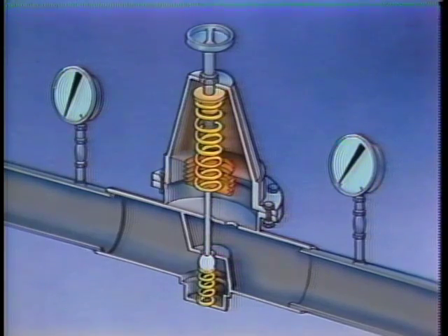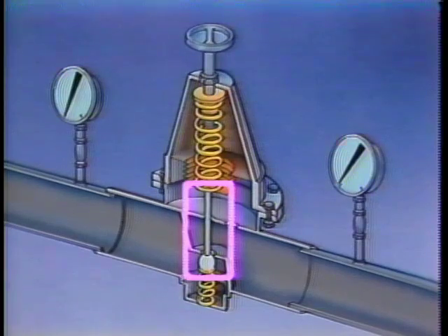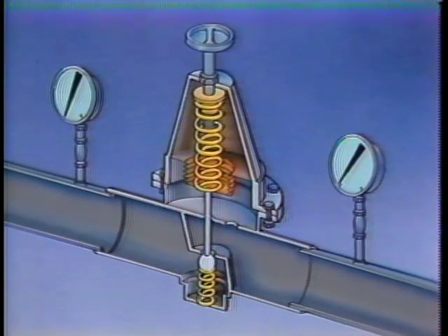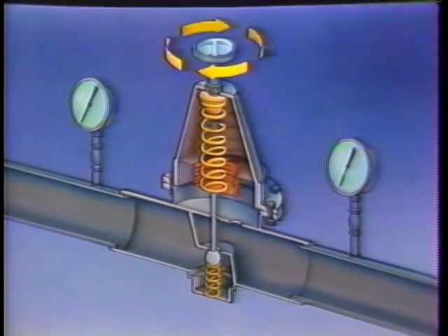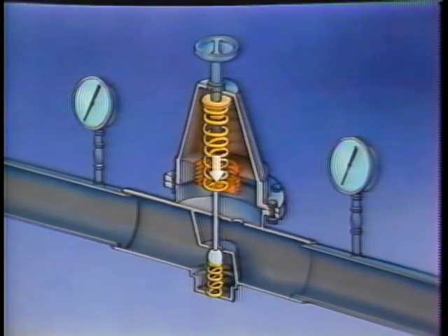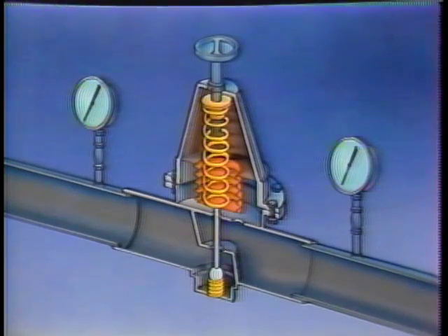The bellows serves a third purpose, that of an operator. The valve is connected by a stem directly to the pressure side of the bellows and moves as the bellows flexes. Here's how they work. Clockwise rotation of the set point screw compresses the set point spring. Pressure from the set point spring on the bellows forces the valve open against the inlet pressure and a valve spring, which maintains contact between the valve and the body.